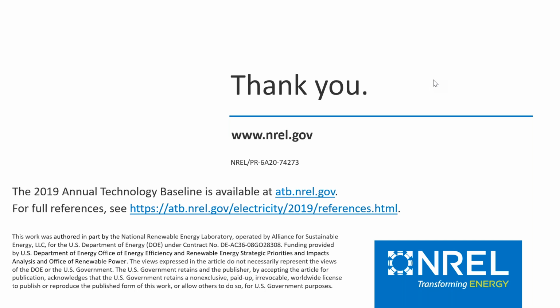Sounds good. Thank you. We have had a similar question come in on the line about the assumed life of battery storage. Wesley, did you want to field that one? Yeah, so our assumed lifetime is, again, largely based on literature, and so we're using 15 years. It varies, so we're assuming 1 cycle a day for our typical battery performance. Battery technologies range widely based on how you design it, what chemistry you're using. So certainly, you could find shorter, longer lifetimes. You could operate it differently to get different lifetimes. You won't find that kind of detail in the ATB, but hopefully that gives you a sense of what we've chosen to represent.